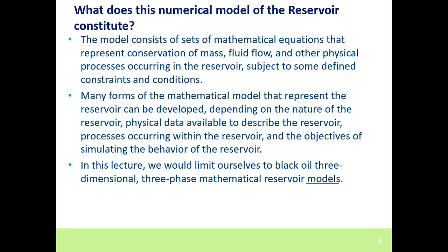So the numerical model consists of sets of mathematical equations, still built on the concepts you are familiar with: conservation of mass, a transport equation, Darcy's law, Forchheimer's equation in some instances, and other physical processes, of course, subject to constraints and boundary conditions.